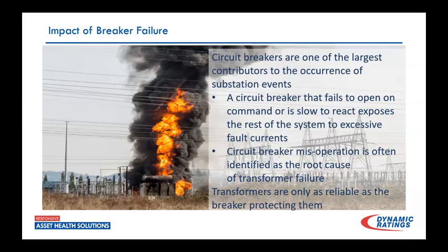The fault was believed to happen somewhere between the low side breaker and the transformer. The low side breaker couldn't clear it. The high side breaker failed to operate. No breaker fail in place. So 6 minutes resulted in a loss of that entire station. It's a 2 transformer station. Sadly, the fault lasted so long, it actually hit the cable tray in the station and burnt the station house up as well. So we were looking at 6 to 8 months of outage over that, just millions of dollars, a lot of line regulators.